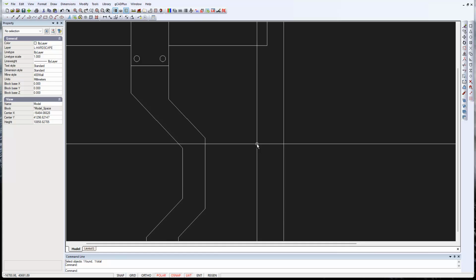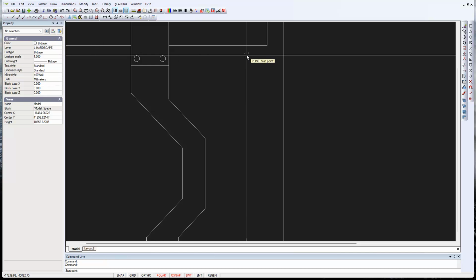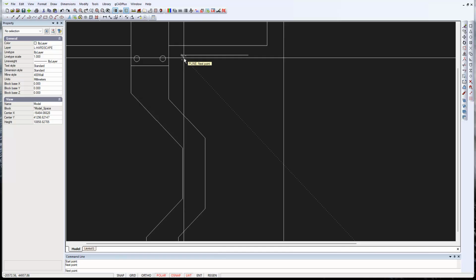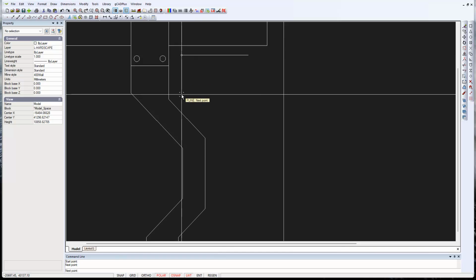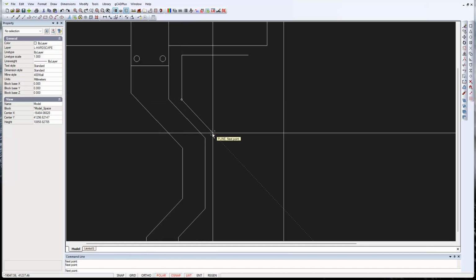The relatively easy way of doing that, and now that you have opportunities to use the offset command, is to start and draw a polyline, and we'll start it from here, and we'll come in, and I've got polar on, so I easily get the horizontal, and I come down. I'm drawing the middle line of what will be an offset polyline.